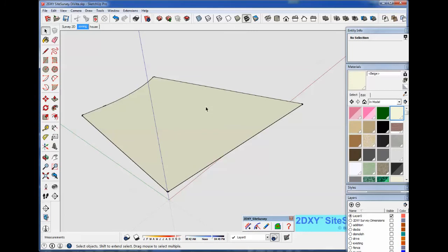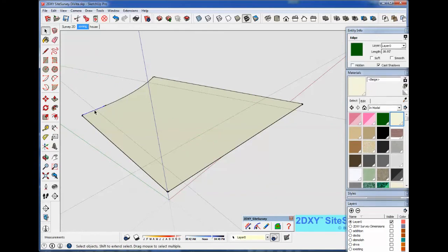I've looked up the regulations, and using the standard tape measure tool, I'm going to create setback lines. There's a 10-foot setback from each of the side yards. I'm typing into the control box in the lower left 10 feet. Another 10 feet here. There's a 25-foot legal setback from the rear. And from the front, there's also a 25-foot setback. But since we have both an edge and an arc, I have to select those and use the offset tool to come back 25 feet.